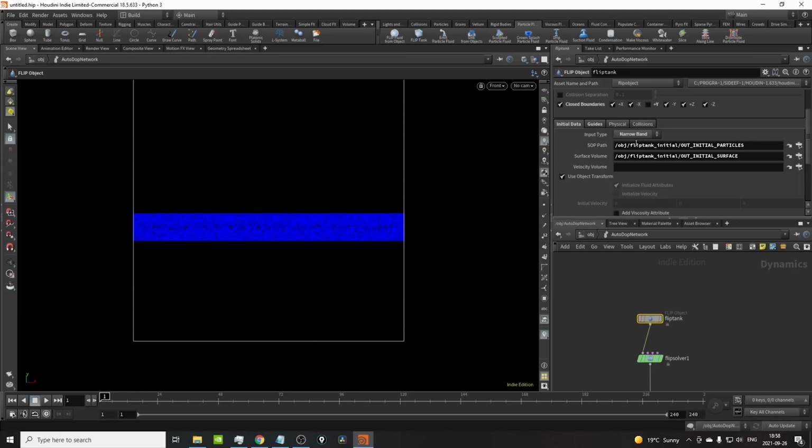Again, because the solver is all volume based, but we're visualizing and operating on particles, Side Effects came up with a really nice solution of just removing all the particles that are not close to the surface of our simulation. Because all these particles are just used for detail, they're used for extra meshing resolution and to carry very precise attributes later down the line, we don't need them down here. All of these particles down here are just wasted. They slow down our computing, right? So with narrowband, we are removing those.